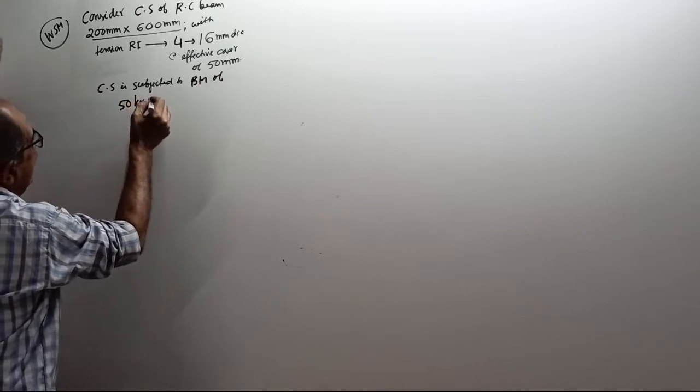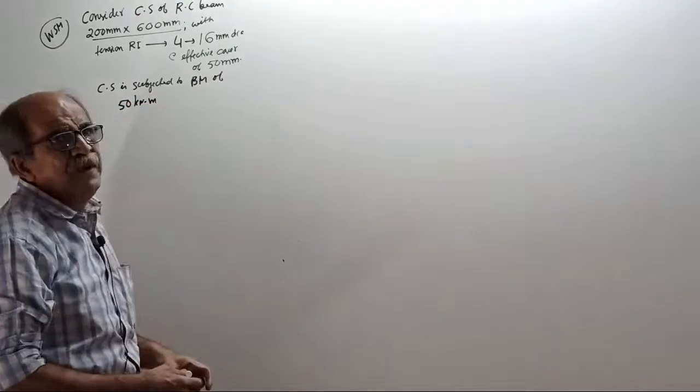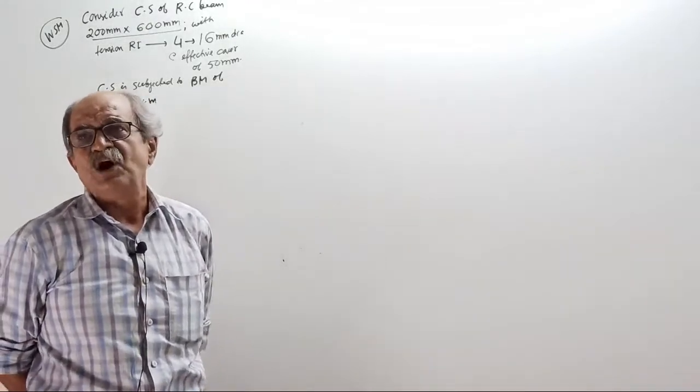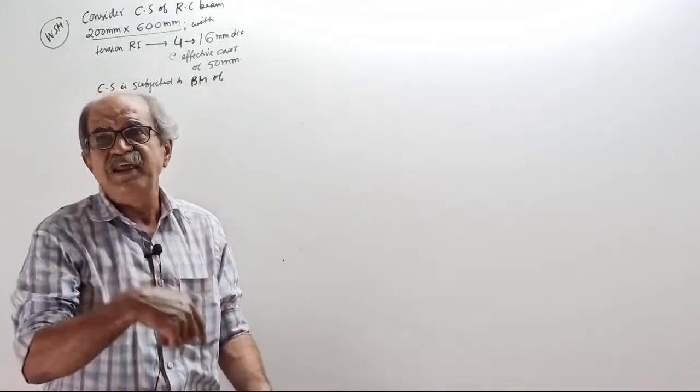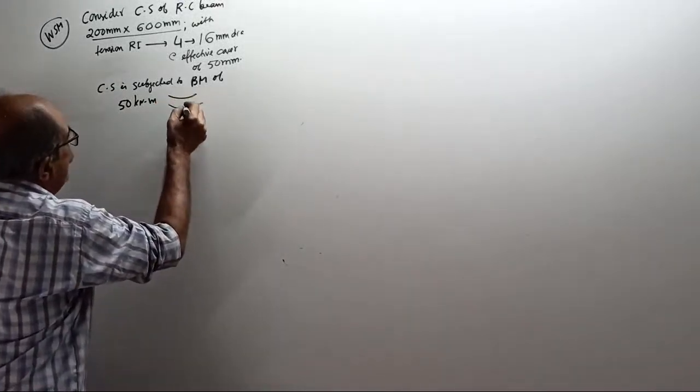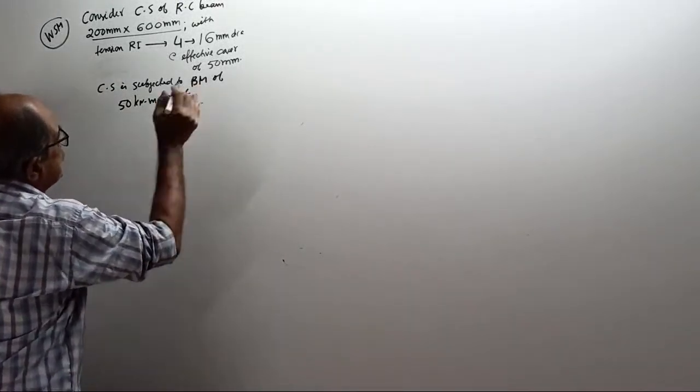Again, some will wonder, how do you know it? How I know it? If I go to a hotel, idli how much cost, dosa how much cost, I get a feeling. Same way it is. 50 kilonewton meter sagging BM. Remember, bottom tension, top compression, over.